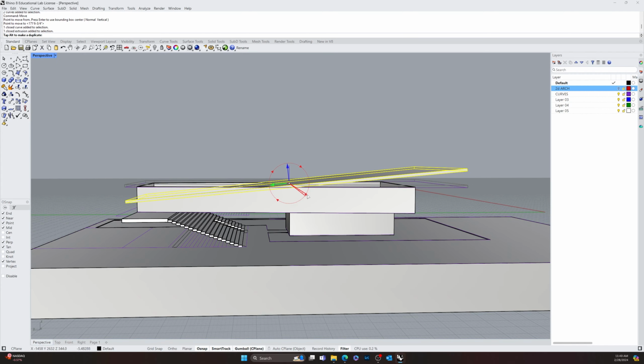So I've got that curve now set, offset right there, and I can extrude it up. So I'm going to go extrude, curve, enter. And then you see where it says to a boundary. I'm going to click on that. And then I'm going to click on this surface underneath here and watch what happens. That now created an extrusion that lines up perfectly with my ceiling here.